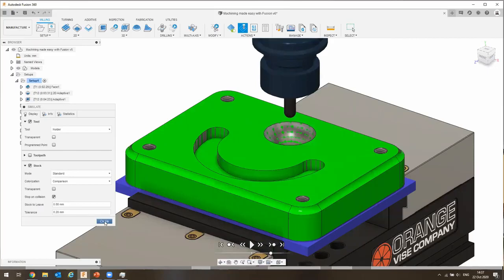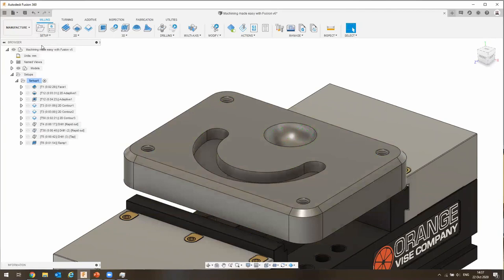What I would then do now is I would obviously turn this around in the vise to be the other way and then machine the bottom off. I'm not going to do that for this instance, but what you would do is you would create a new setup. So it would be a different setup with a different Z direction.